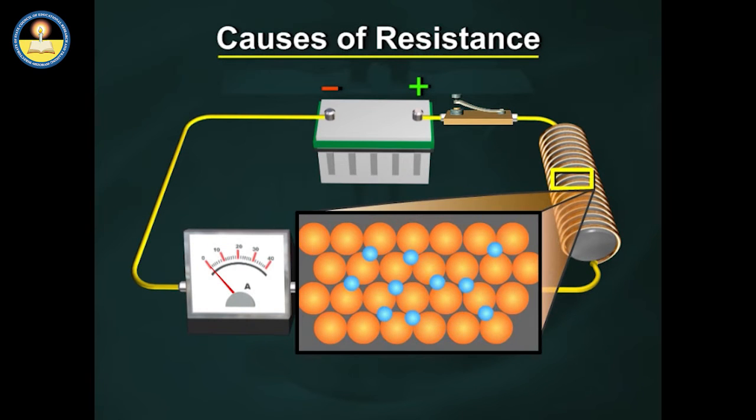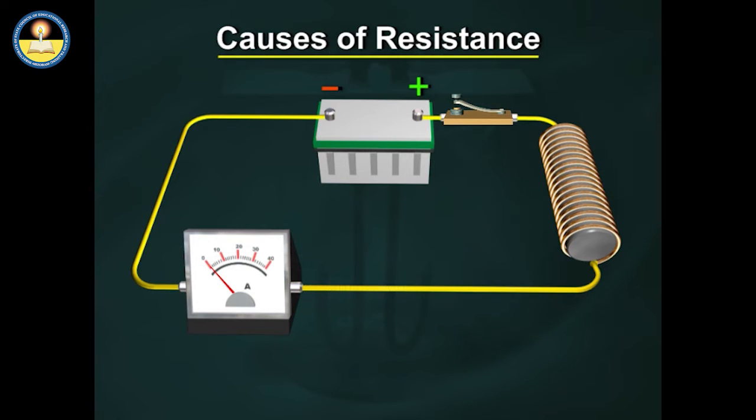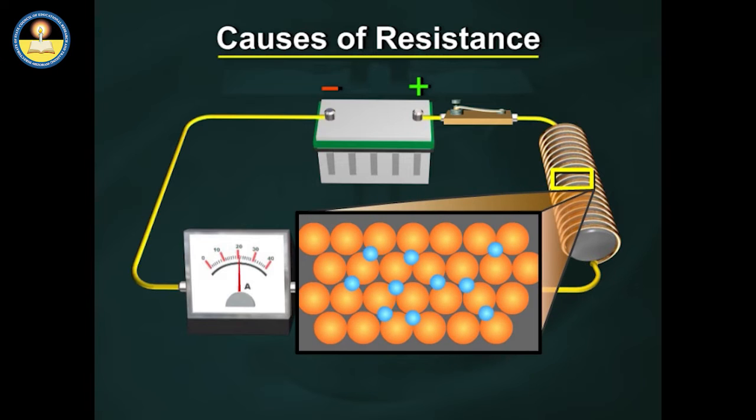Let us make a motor. Take a 1.5 volt torch battery, 1 meter of insulated copper wire used for motor rewinding, 1 magnet, 2 metal file clips, 2 rubber bands 1 centimeter wide cut from an old bicycle tube, some thread and ordinary hand.